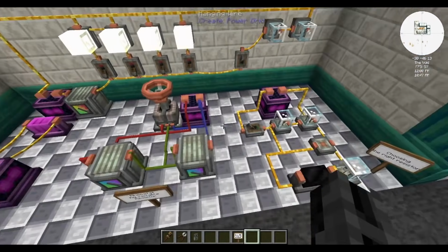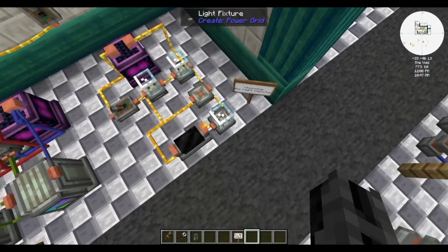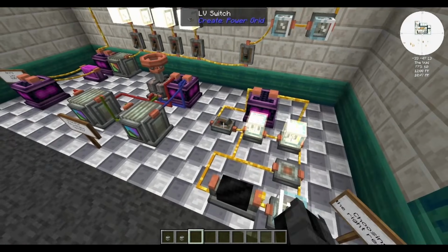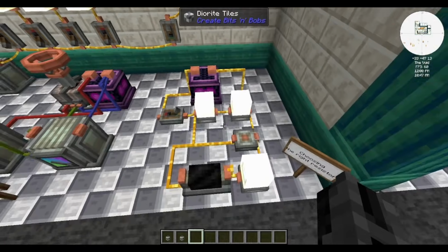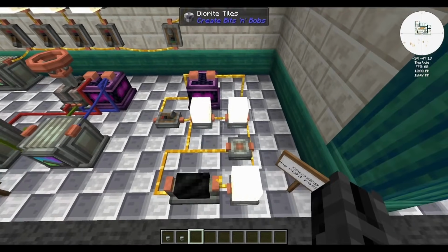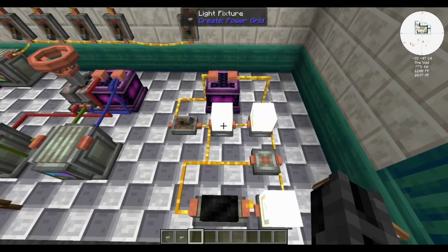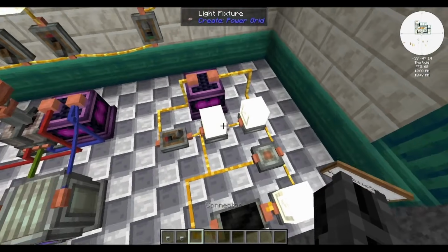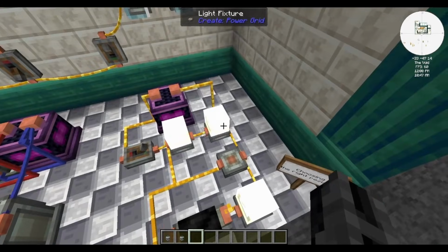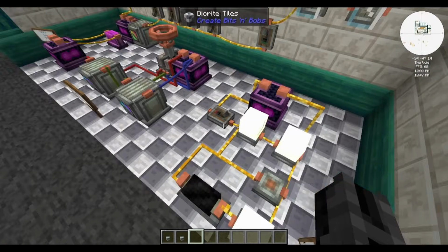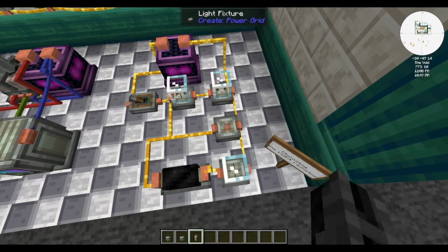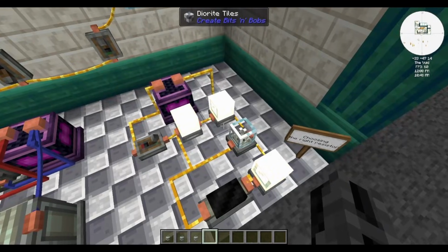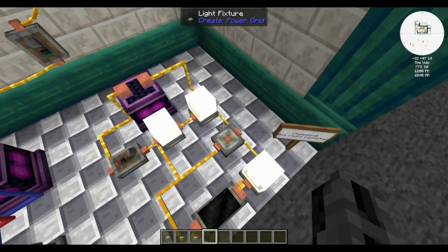And then we can move on to the last example with Ohm's law and Kirchhoff's law, and that is how to choose a resistor for a given circuit, for a given load. Here we have a 24 volt source and two 12-volt lamps in series, and they light up no problem. But if we put down a 12-volt light bulb on its own, it's going to blow up because the voltage is too high for it.